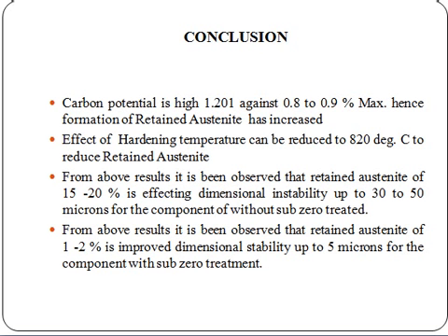From the above results, we observe that retained austenite of 15 to 20% affects dimensional instability up to 30 to 50 microns for components without sub-zero treatment. From the above results, it has been observed that retained austenite of 1 to 2% improved dimensional stability up to 5 microns.